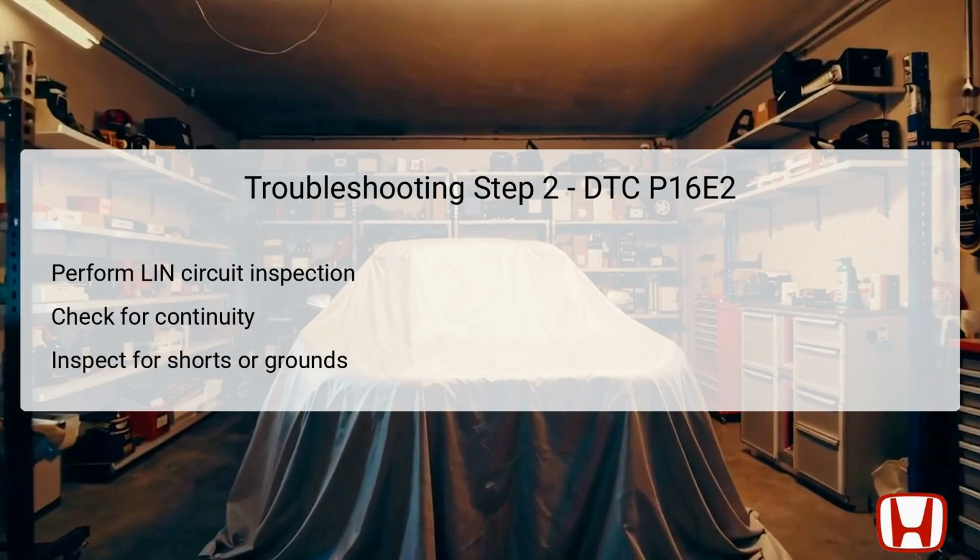This step will help pinpoint if there is a fault in the wiring or if any components connected to this circuit are causing the issue. A thorough inspection of the wiring harness and terminal connections is also beneficial to visually identify any signs of damage.